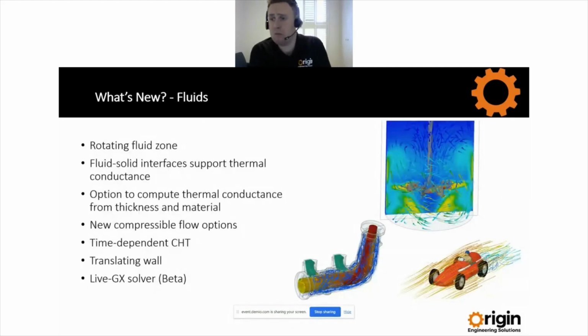Arguably, there have been a few more things added on the fluid side, which Tim alluded to right at the end. Being able to model rotating fluid zones was really important for a lot of our customers, especially if you've got electronics components with fans, or you're dealing with pump design. That sort of stuff is really important. And there are also some new compressible flow options allowing you to combine compressible flow with porous media.